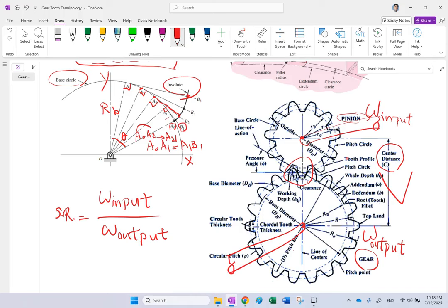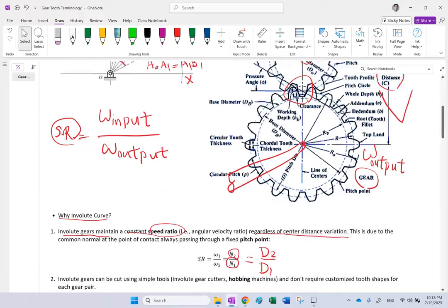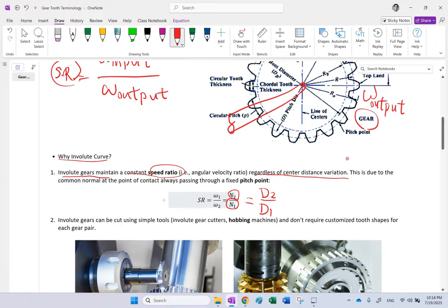And that's when you see that instead of this speed ratio being a constant number, it is going to start oscillating and being variable. Now, is that a constant number? Yes, based on what I showed you, it's number of teeth 2 over number of teeth 1. And since n2 and n1 are constant numbers, you expect this speed ratio to be a constant value for 2 specific gears.